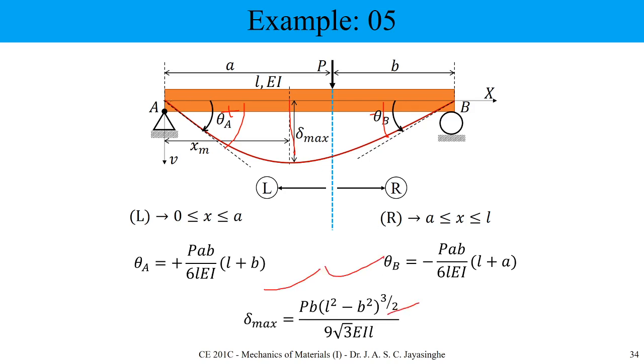This is different from your previous example because here we work with two separate parts, because we cannot express our bending moment variation from one particular equation. We use two sets of equations. When you have two sets of equations, we need to create continuity. To establish that continuity we use continuity conditions, and here we are using two sets of continuity conditions, V and theta. Okay, and this is the end of our session today.